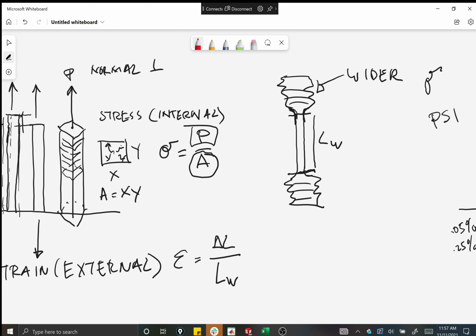So exactly right. What he said is that it's this cross section. If every single one of these cross sections is taking the load, it doesn't matter how many. They're all taking the same load. It doesn't matter how many cross sections you have. We also know it mathematically because there is no length in this equation, right? So that's how we get suspension bridges, right?